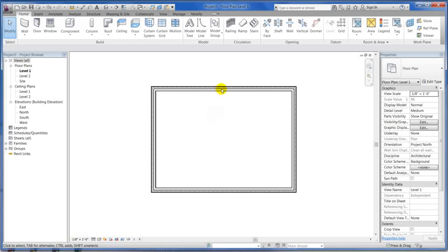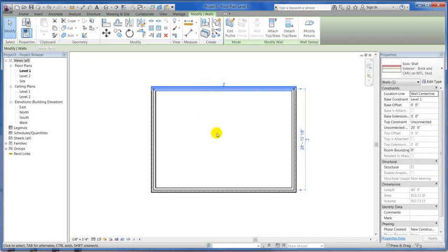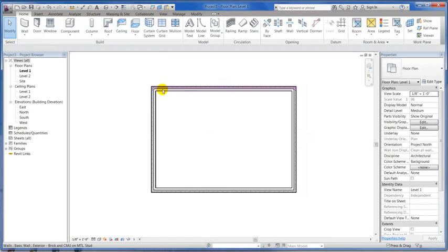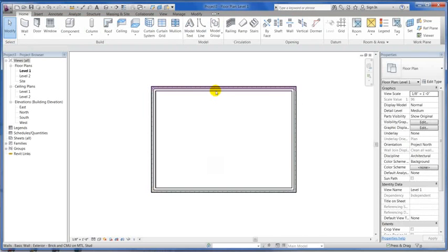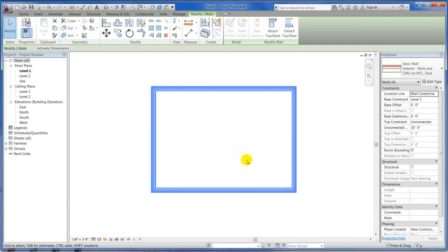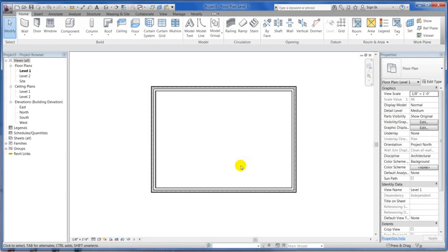I'm just going to run through this real fast because if you can't select stuff, of course, you can't modify anything. If you'll notice, I have not clicked on anything yet. Just hovering over it highlights a wall. That is a pre-highlight. So I can do that and of course select. But what I can also do is if these walls are chained together, which they are, you can see they're all connected, I can highlight over one wall or object or anything, hit the tab key, and anything that's chained to it will automatically select. Then I select them and now they're all selected. So that's a tab select. Tab on it, boom, they're selected. So that's all I wanted to go over in the first video.